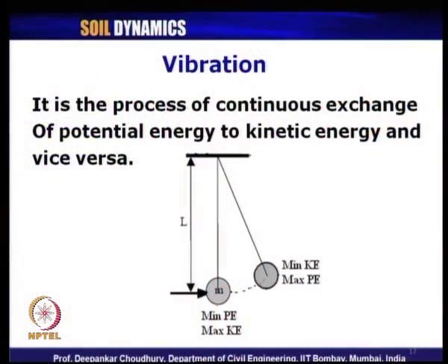Let us look at the slide. Vibration is the process of continuous exchange of potential energy to kinetic energy and vice versa. So, in any system, if there is continuous exchange of energy from potential to kinetic energy or from kinetic energy to potential energy, due to the application of some time varying load, then we can say the system is vibrating, and then it can be considered as a dynamic load.